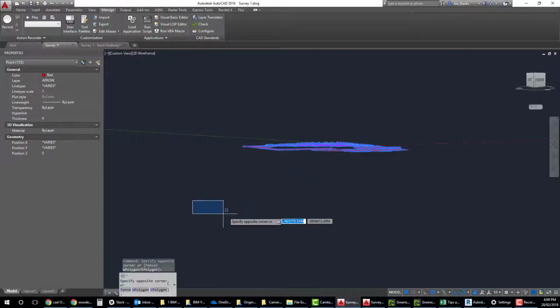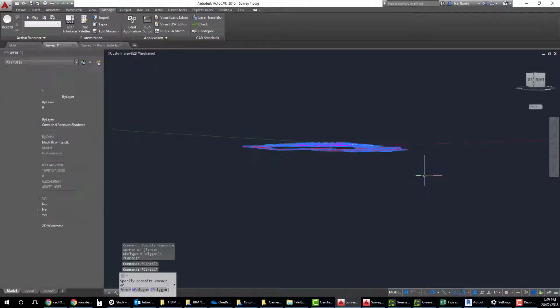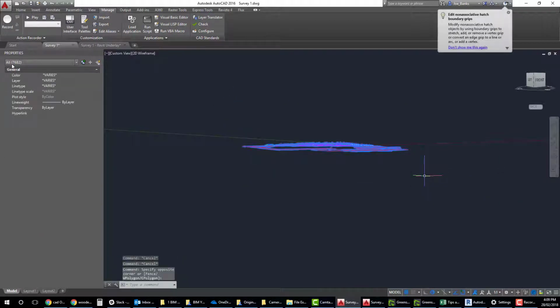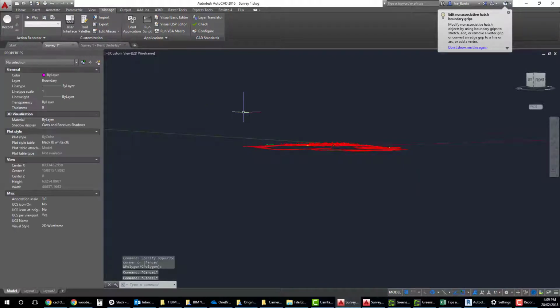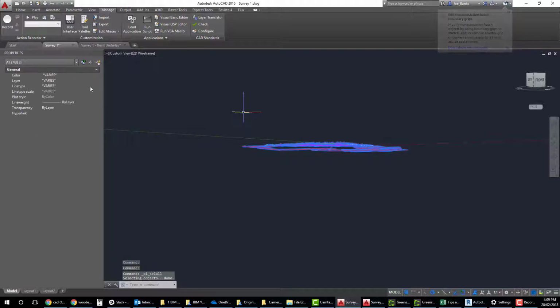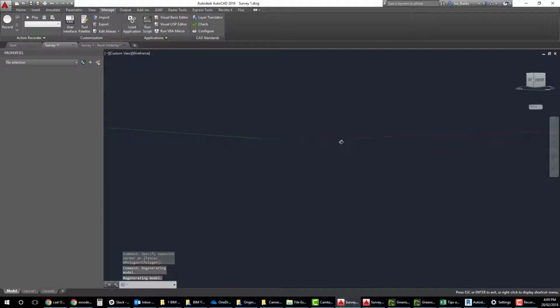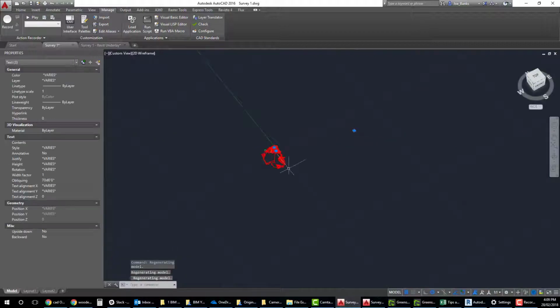The other thing you can do here, if you've got lost objects you're trying to find, if you do a bit of a window select there, you can see you've got 7682 is that number. If you go Control A, that's selecting everything in the file. You can see you've got 7685. So see, there's 3 objects that are just not part of that selection. They're just a bit of text that's got a really big origin.